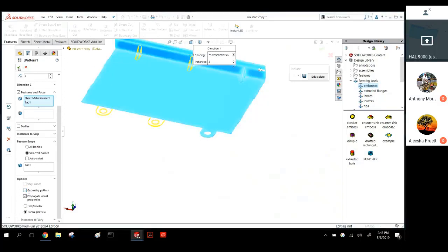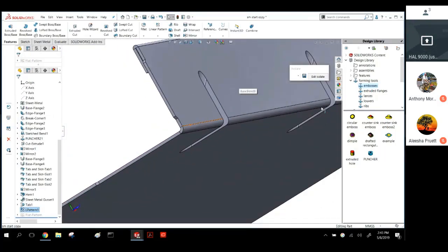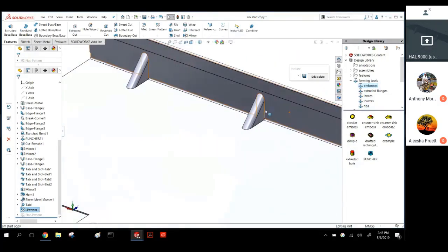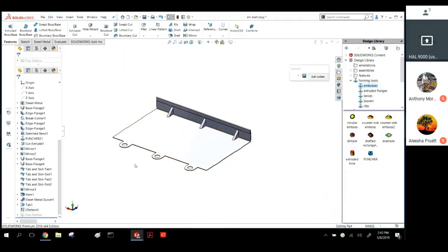What geometry pattern does is it doesn't try to resolve anything. It doesn't pay attention to any of the end conditions or anything like that. It just tries to give you the same XYZ shape. It's having problems with that because this thing actually needs to remove material off the back of this thing and put material on the front. So it can't do a geometry pattern. It has to actually resolve every one of those sheet metal gussets.